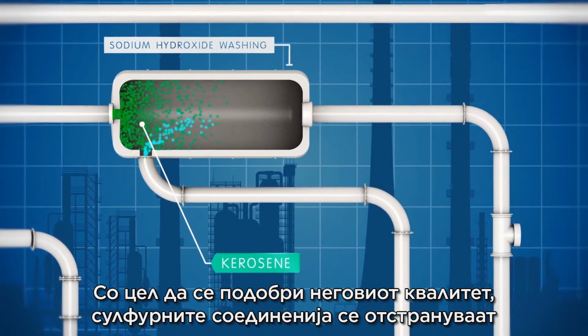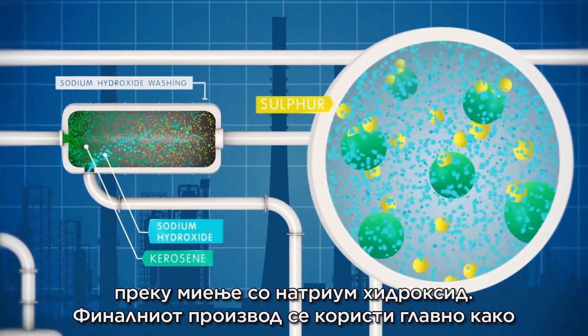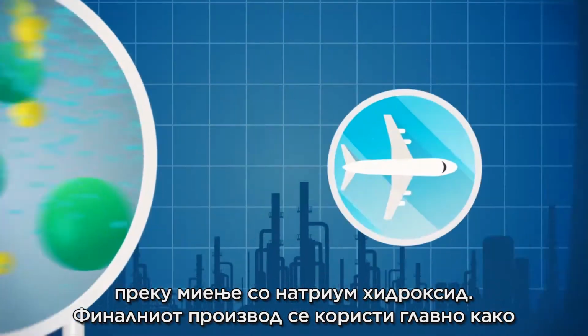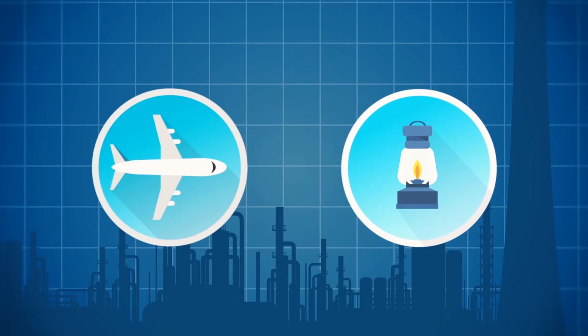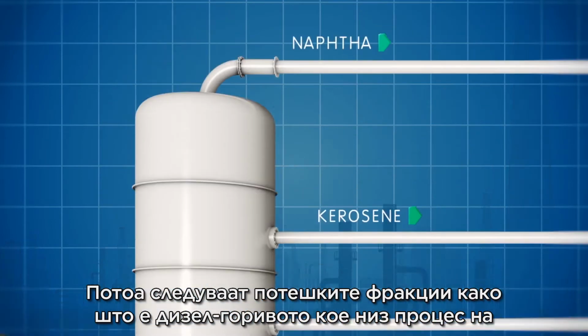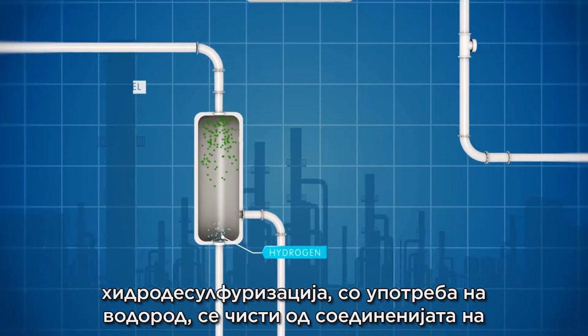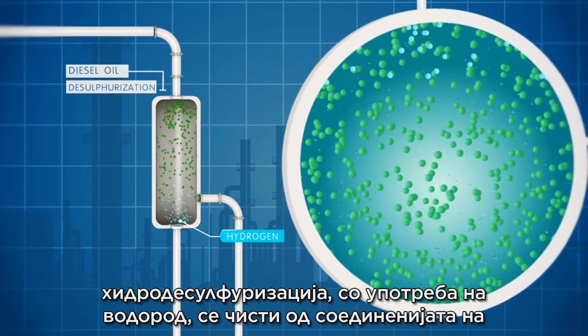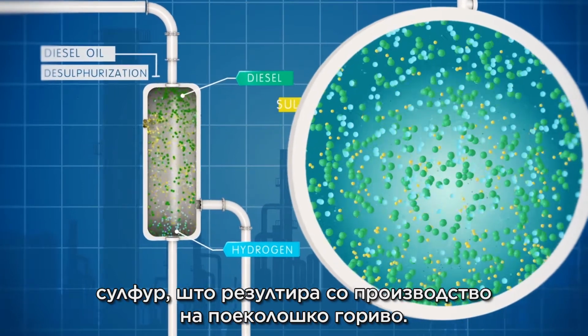In order to improve its quality, sulfur compounds are removed through washing with sodium hydroxide. The final product is used mainly as jet fuel, as well as lamp oil. Heavier fractions, such as diesel oil, follow, and through a desulfurization process with the use of hydrogen, are cleaned from sulfur compounds, resulting in the production of a much more environment-friendly fuel.